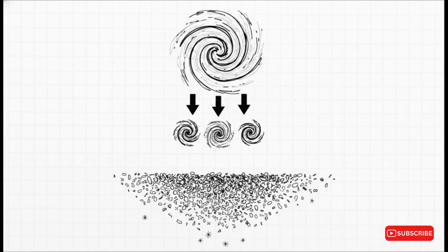This turbulence sets off what we call an energy cascade. It's like a cosmic relay race. Massive vortices break down into smaller and smaller eddies. Kinetic energy enters at the very largest scales and transfers downward with virtually zero energy lost. It keeps cascading until the eddies reach the microscopic level, the Kolmogorov scales, and that is where the energy is finally burned off by viscous friction.